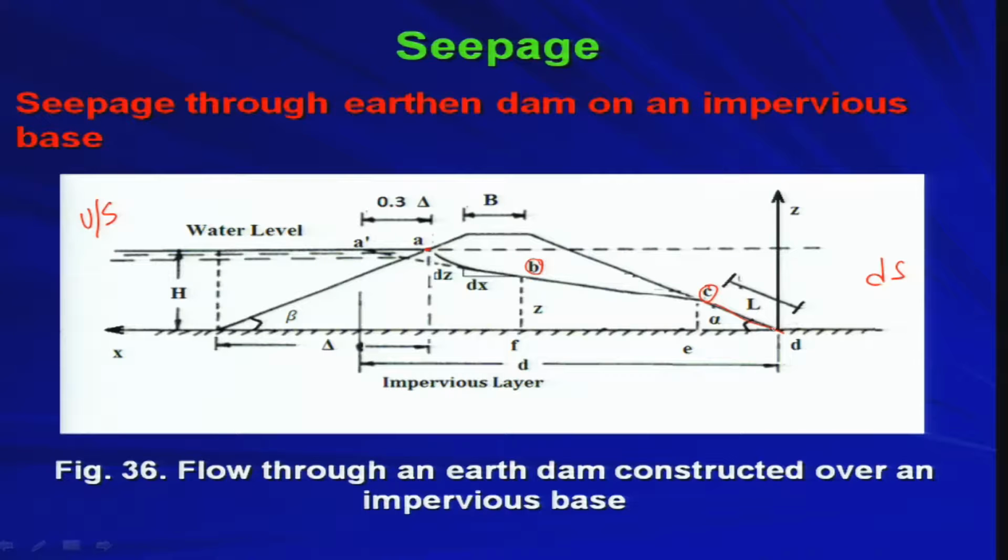So, basically the topmost flow line is nothing but A, B, C as well as D, the topmost flow line along which the flow is happening. Below that line, up to the impervious layer, the soil flow will be occurring, and above A, B, C, D you do not have any flow. So, you can construct the flow net for that, there is no issue, because once the flow is happening you can construct the flow net.